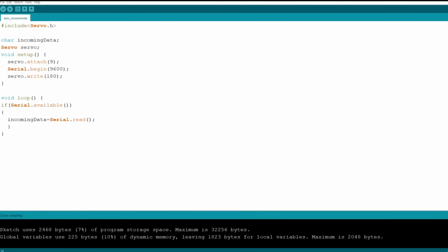As you know, our arm will have 3 different movements. It will perform these movements according to the incoming A, B and C signals. For example, if the A signal is coming, we will set our servo motor to 45 degrees. That is, it will be completely closed. So let's do this operation now.